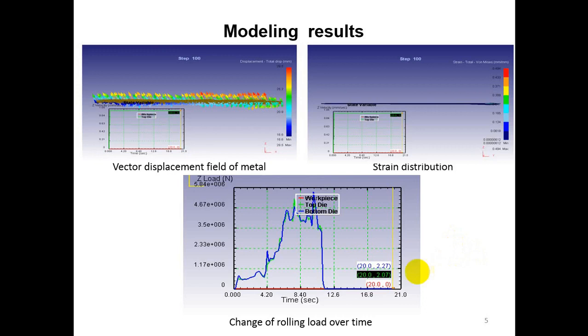As you can see, the rolling force varies over time unevenly. This is explained by the fact that the rolling process is uneven because the amount of reduction can change due to the presence of various micro-roughness, both on the surface of material and on the roll.